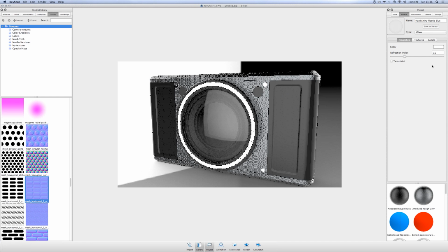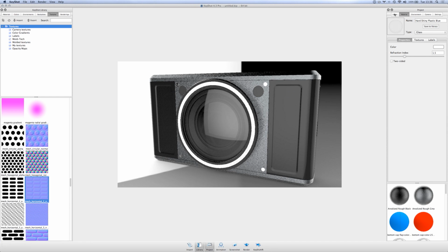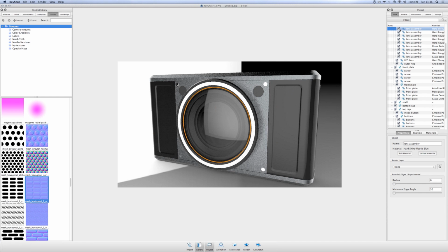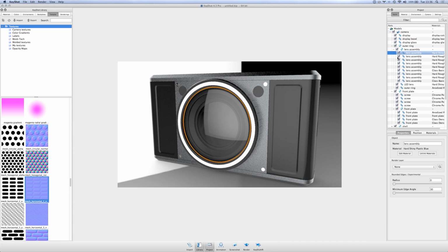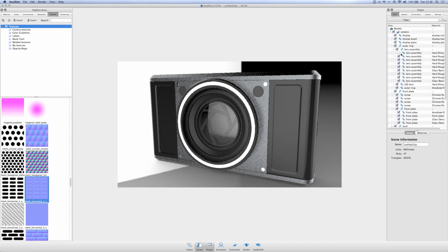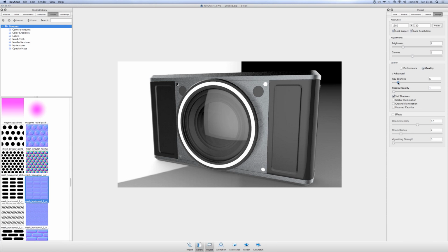And one thing I want to mention briefly here as well. If I turn off this outer piece of glass, you'll notice that I've got more objects under that piece of glass. When I turn my glass on, I can't actually see those. And sometimes, let's say you're working with glass or transparent materials and they're not lightening up, they're staying too dark and you don't necessarily know why. I want to make sure to call out that this has to do with your ray bounces in the scene.